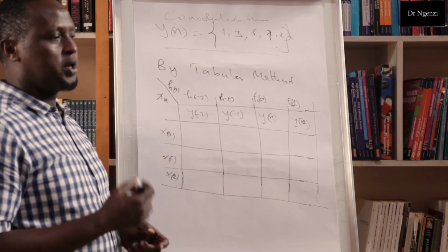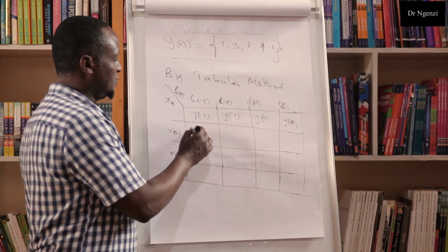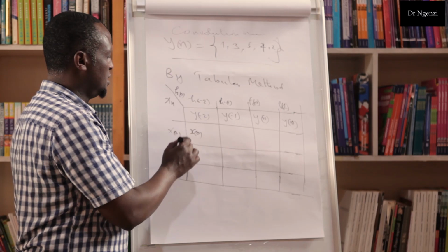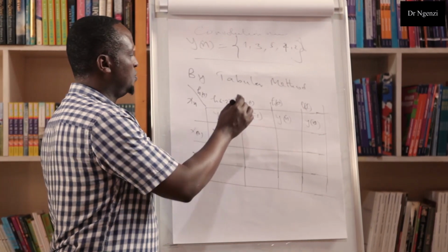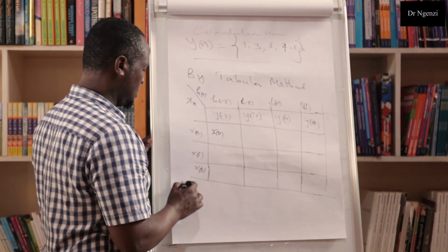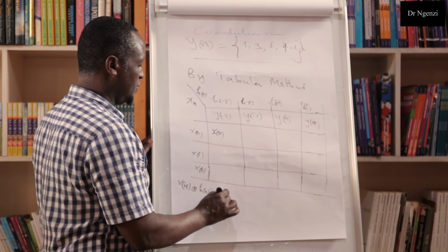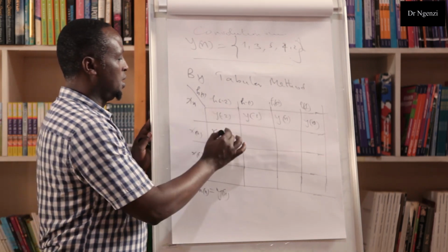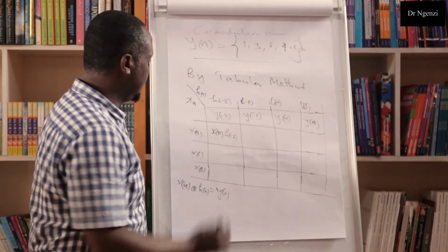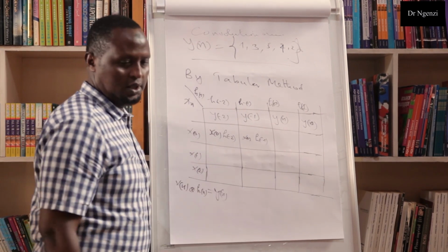So you are going to multiply and add the values of x. For the first time, it's going to be x of 0 multiplied by this. Then you multiply horizontally by the x value with x of n. Remember, x of n convolved with h of n is going to be y of n. So the response here is going to be h of this. So we will multiply by that. Then multiply by this: x of 0 into h of -1, and then that way.